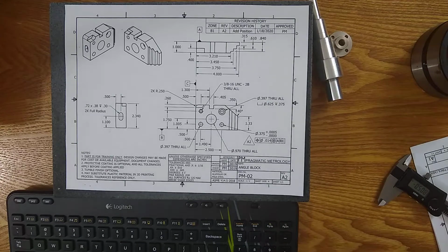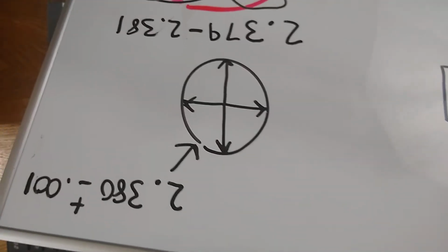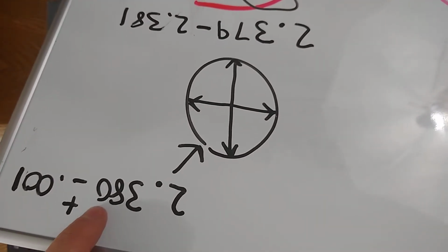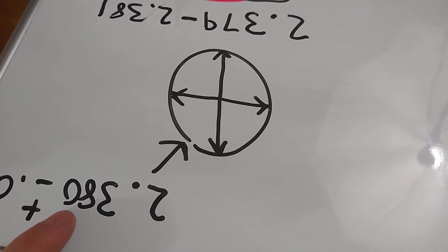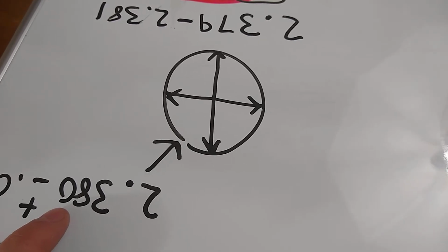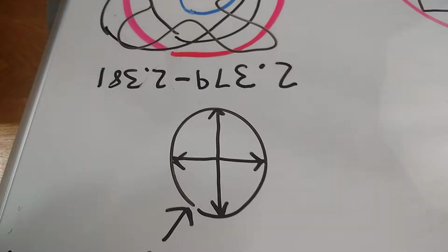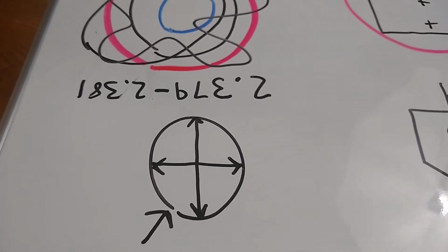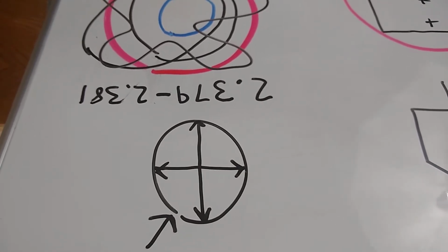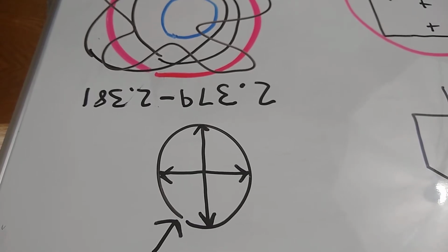What I forgot to say, before we move on: this is not called out to be a GD&T call out. This is the same thing as circularity or cylindricity, which are GD&T call outs. When you do this style of check, there's kind of an implied GD&T form error. Even though it's not stated, you're saying every point needs to be within this window, which is exactly what circularity says.